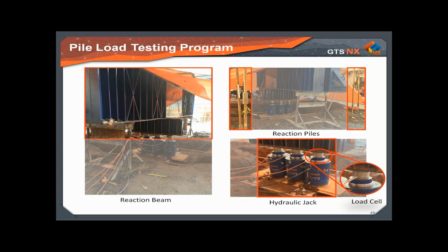The geotechnical engineer starts with the design of the pile load test. So we define the type of pile, the diameter, the length, the maximum test load, and also the reaction system. We followed up the execution of the test and later interpreted the results.